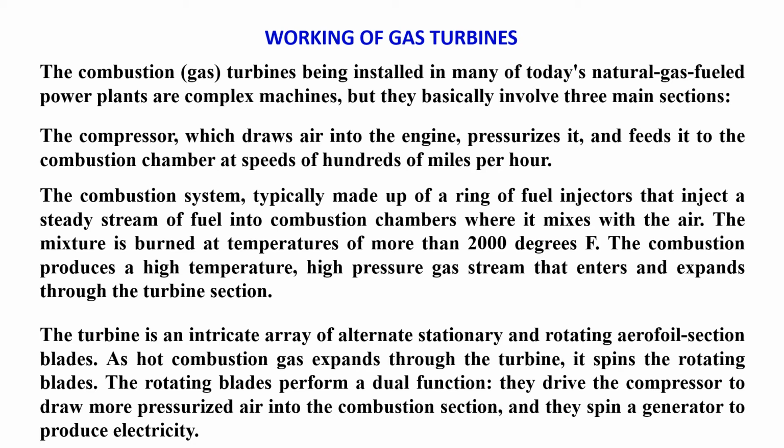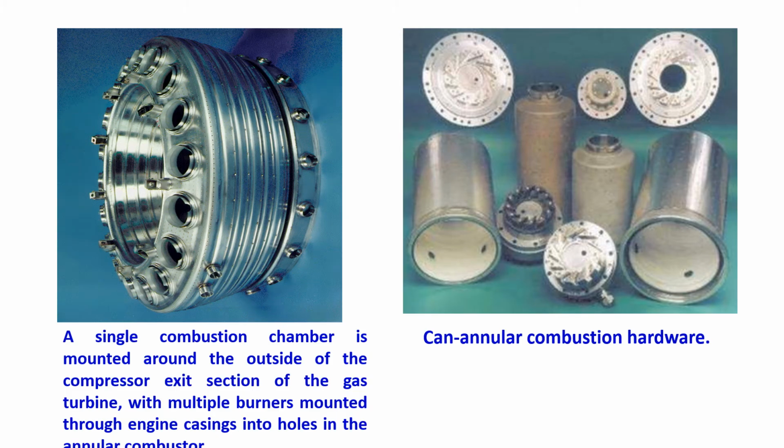In the gas turbine, there are stages of expansion taking place, like an array of expansion: stationary blades and rotating blades, stationary and rotating, likewise. So stage-wise we are generating the speed. That is another advantage of this type of gas turbine. You can say this is the practical example.